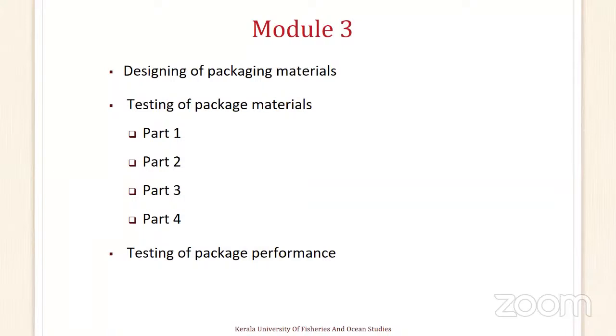In paper, we talked about the grammage, thickness, Cobb's value, and very important tests like tear, puncture, and bursting strength. I hope all these things have been clear to you, especially from the live practical demo videos that we showed. Plastics also, we have a number of testing methods that we used. We talked about the thickness of plastics, and we talked about the dart impact, tensile strength, seal strength, all of which are very important, especially after you pack your food. You need to see that your package will not give way or the products inside will not get damaged.